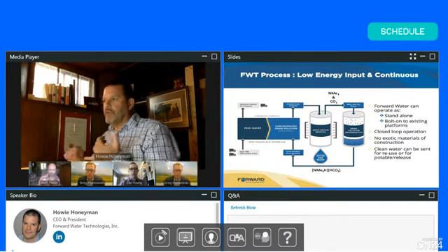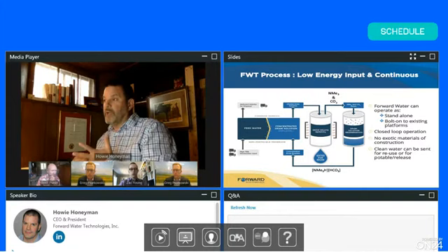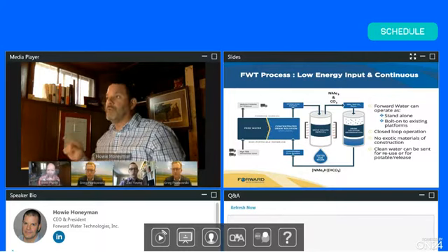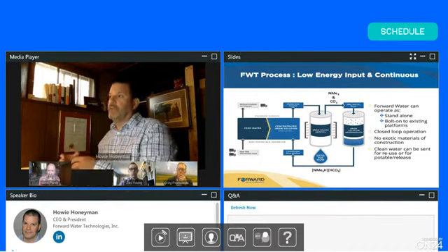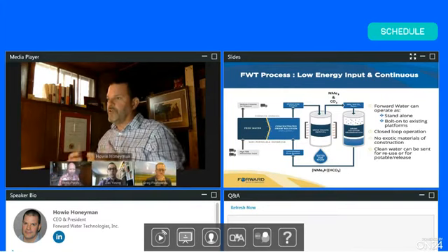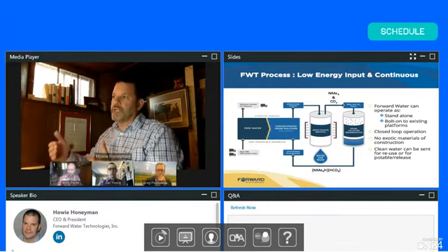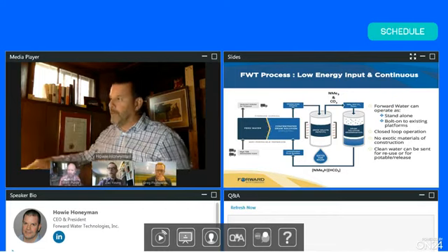So what have we done? We've extracted water from dirty water using a low energy process. We've done it using a chemical-driven osmotic pressure that uses chemistry that can be recycled over and over again. So it's closed loop: a low energy process using essentially off-the-shelf materials and equipment. So we think this is going to lead to a very economical process for treating high strength wastewater.